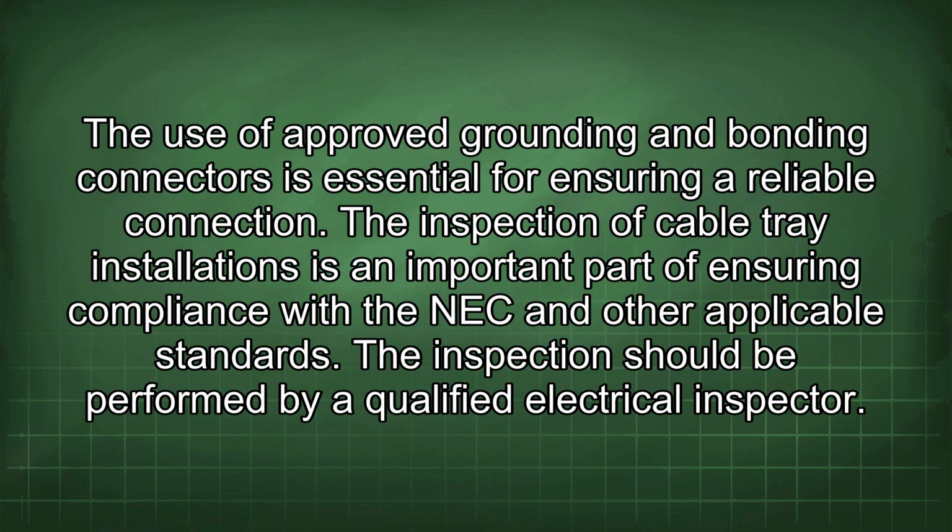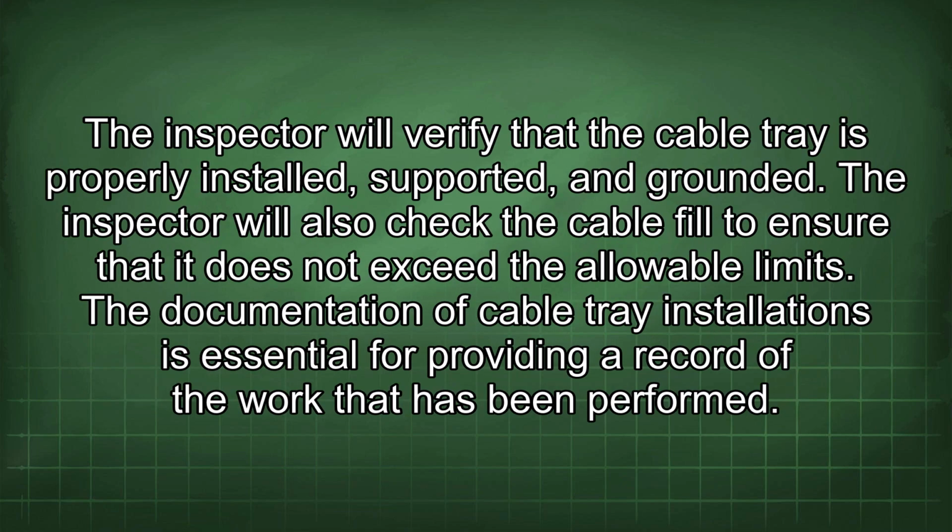The inspection of cable tray installations is an important part of ensuring compliance with the NEC and other applicable standards. The inspection should be performed by a qualified electrical inspector. The inspector will verify that the cable tray is properly installed, supported, and grounded. The inspector will also check the cable fill to ensure that it does not exceed the allowable limits.